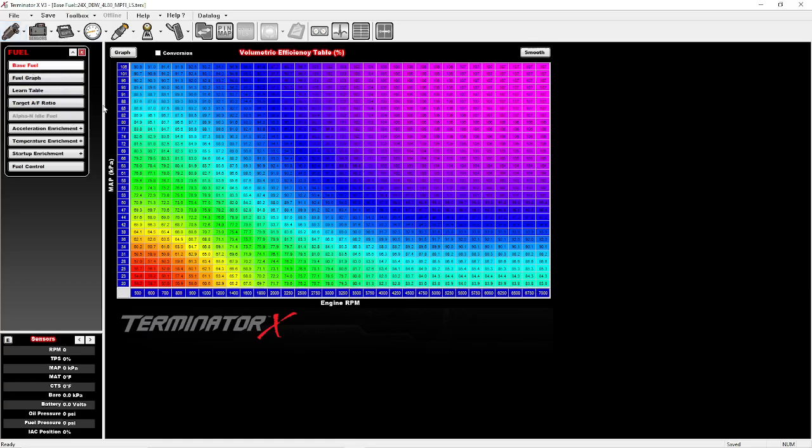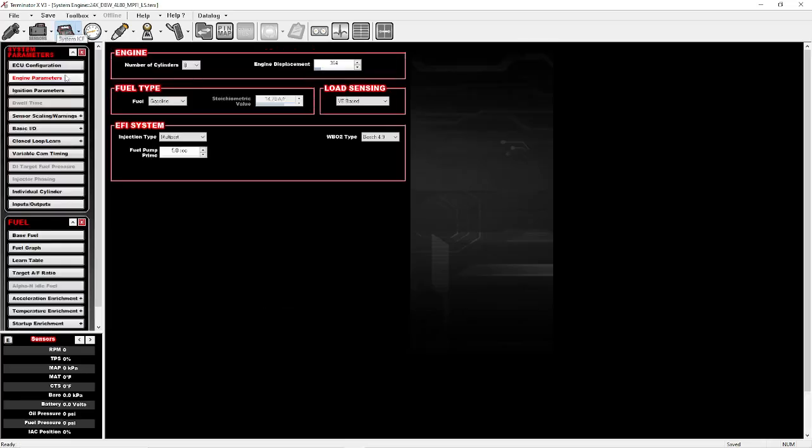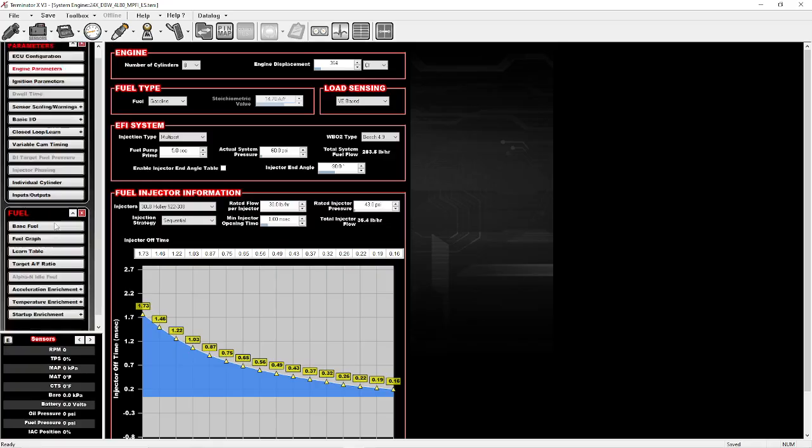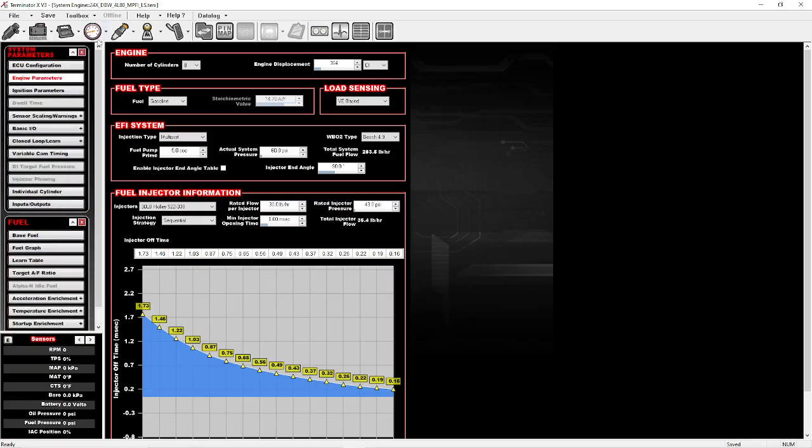So you have a standalone ECU here. You have your fueling map, you have your sensors, you have pretty much your system of how everything's going to be configured, how everything's going to correspond. It's still, again, pretty basic overall. You got your spark tables, your transmission if you're utilizing an automatic, your drive-by-wire. So pretty much you're controlling your throttle, your ignition, your fueling.